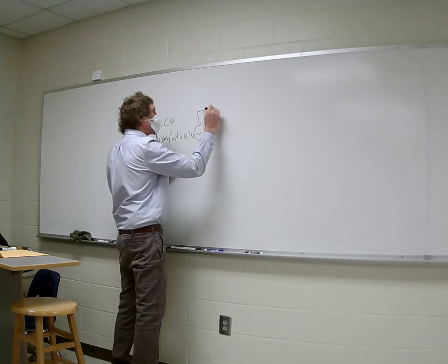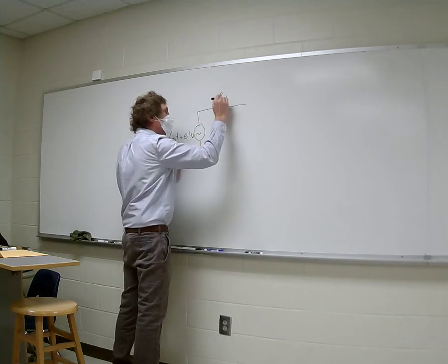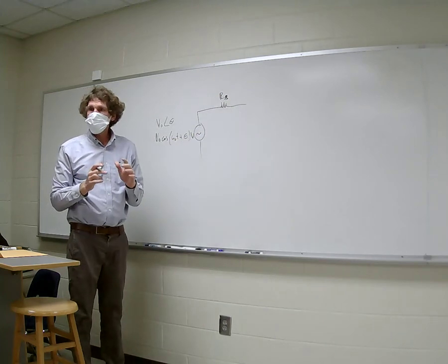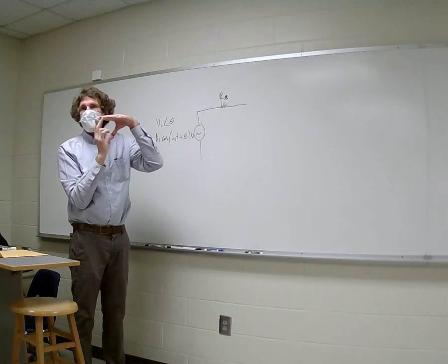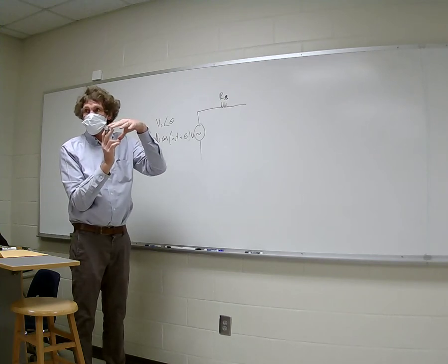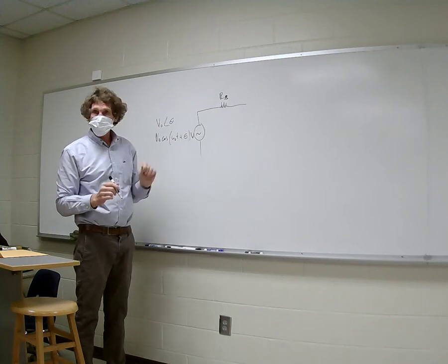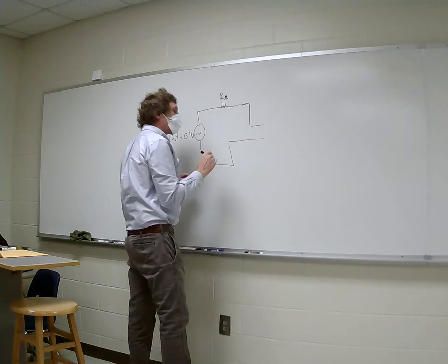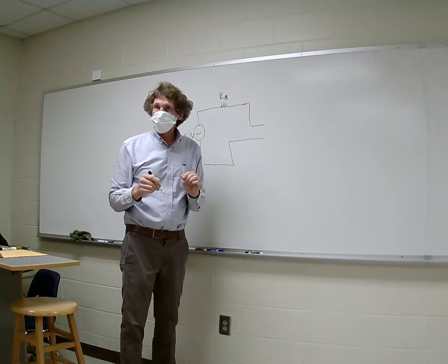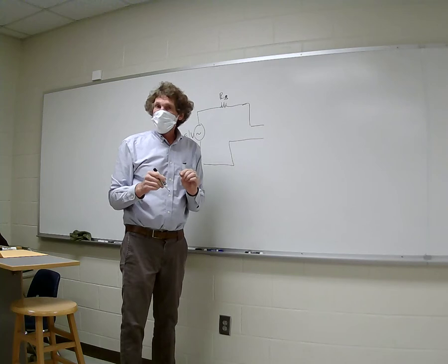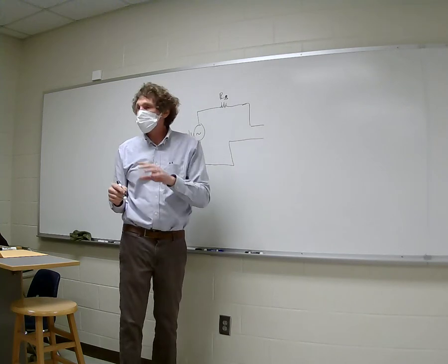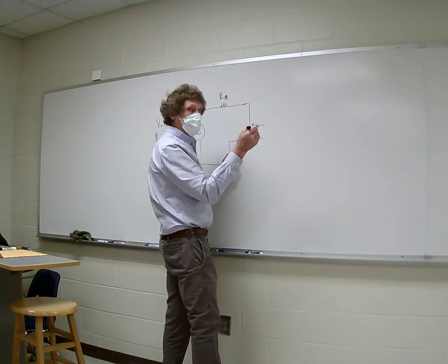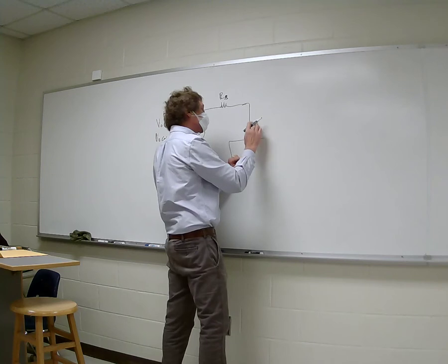Now I'm going to put some resistance here. That's a source resistance. And this is a typical thing you would see if you try to drive an antenna with a voltage source in your labs. This is what it is actually represented by, a voltage source with a source resistance. Now I'm going to put on the antenna. So far we can put on a short dipole or a small loop, or any combination. You don't need to know the radiation resistance of the short dipole or small loop, but for kicks, I'm going to put a short dipole here. We'll do it that way.